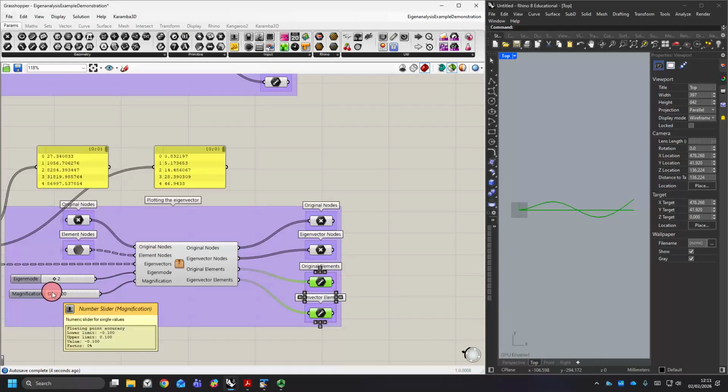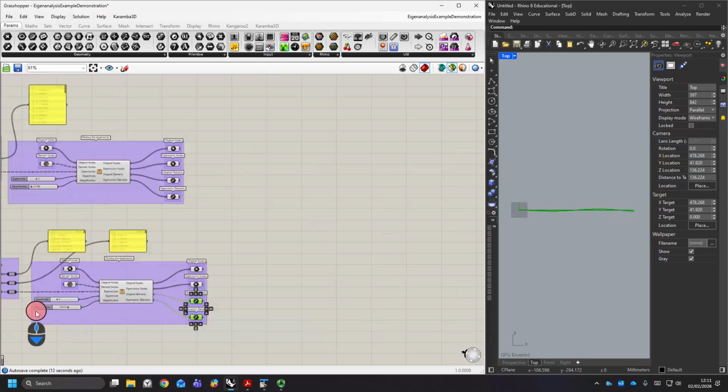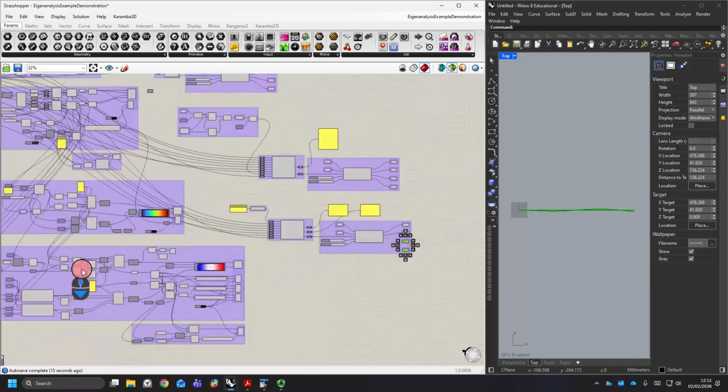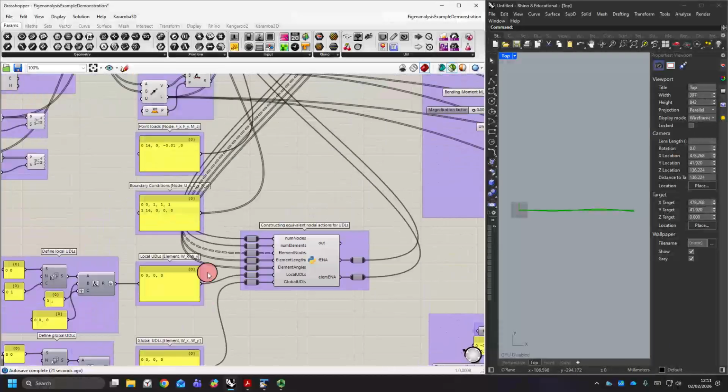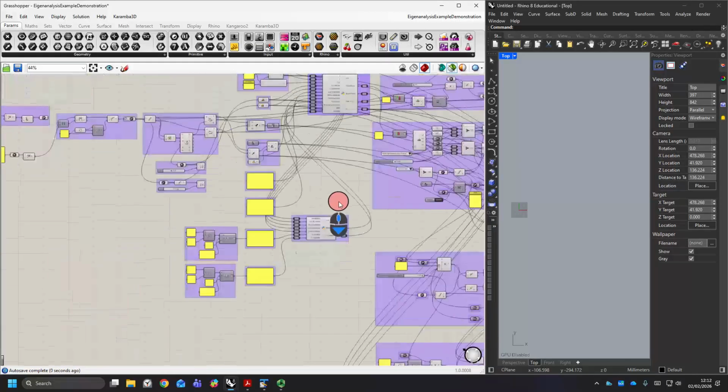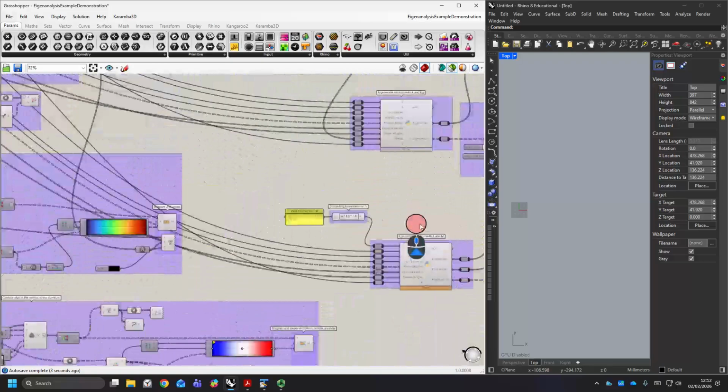If you want to get an idea of how the actual sort of vibration might work, or how it would look, obviously we can run through the relative magnification. So that kind of gives you an idea of how your structure would be oscillating. So we can just go back here. So although the cantilever is the very commonly chosen example, we can do a simply supported beam as well. So just restricting in the y-axis there, obviously removing the rotational constraint.